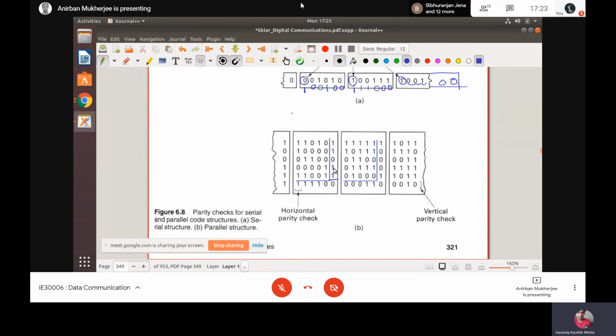And in this one 2, 4, so an even number of ones are already present, I will put a 0. So this is a parity, that is also parity. Now my block size is n plus 1 into n plus 1. Earlier my coded block was n plus 1 cross n plus 1, but my message block was n cross n.